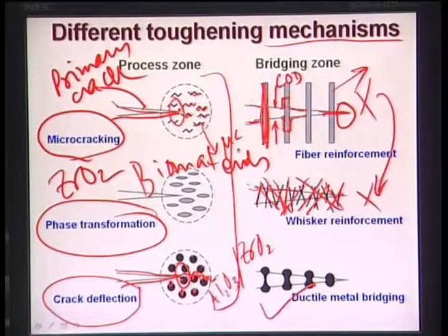However, from these two process descriptions, you can immediately see that in the case of fibers, the toughening will be more compared to whiskers, because in the whiskers case the aspect ratio is reduced, and therefore the hindrance to crack path propagation that it provides is also much less.